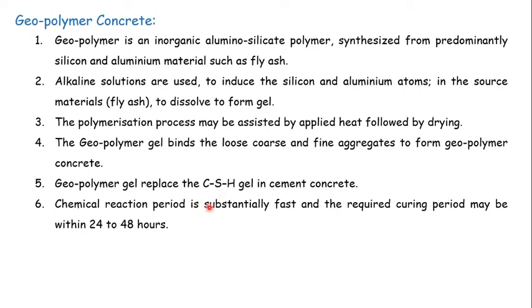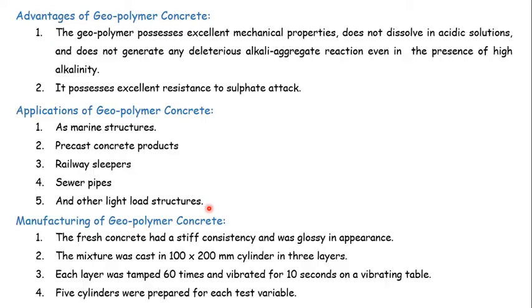The chemical reaction period is substantially fast, and the required curing period may be within 24 to 48 hours. Instead of calcium silicate hydration, the reaction in geopolymer takes place at a faster rate. That is why we require a curing period of only 24 to 48 hours.